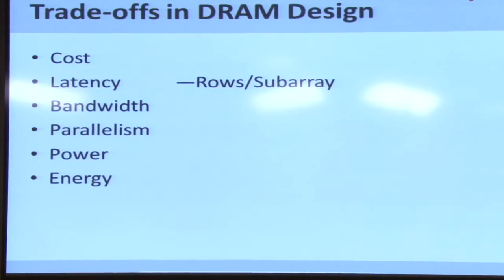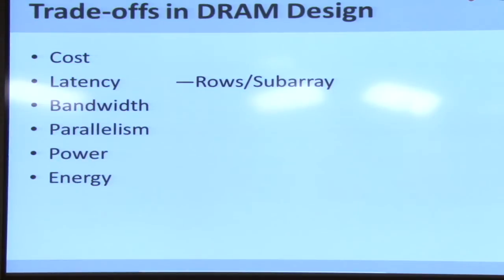You can get 8 bits of data from each one of them and make 64. Absolutely, right? So in some sense, the primary reason for putting more chips on a single rank is bandwidth, right? You want to get more bandwidth out of the entire system, right? So if you actually go to embedded processors, they have fewer chips per rank, right? Because there you want to reduce.